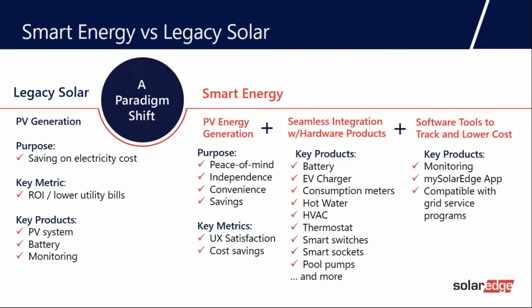So sure, you could use it as just a PV inverter. There's no reason you couldn't use it as a PV inverter. But then it gives you this ability to upgrade. And after the fact, after you install it, if your customer says to you, I want to install a battery, I want an EV charger, I want a smart hot water heater, it's got all those capabilities baked into it. So the upgrade path becomes instantly easier because you're not worried about running another 2-pole breaker to the main panel. Everything is connected through the Energy Hub inverter.